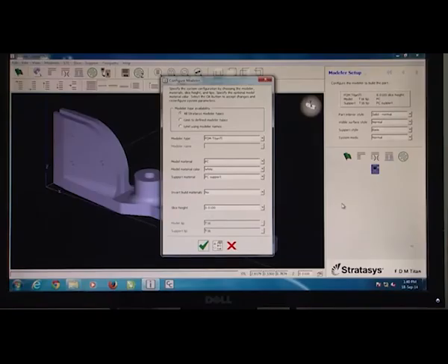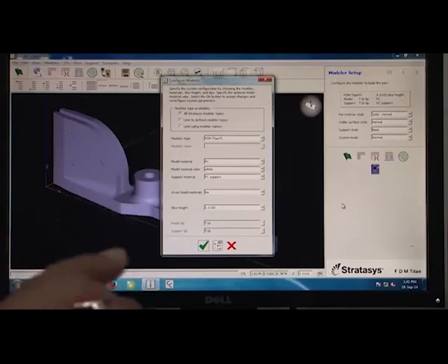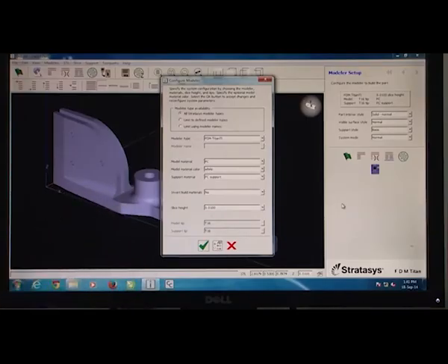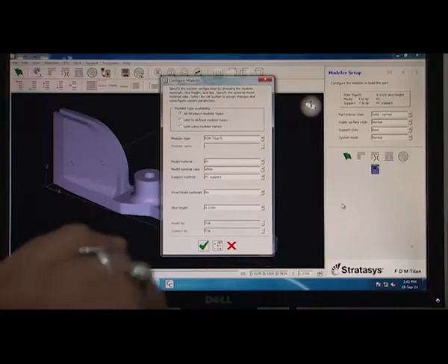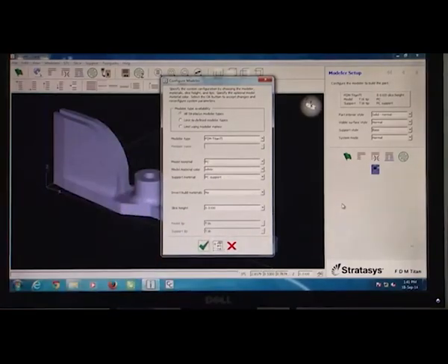We have to remember that there are about 4 nozzles in this system which has been delivered or specified by the manufacturer, and they are classified as different types, starting from T10, T12, T16 and T20. Each of them has a different orifice diameter, because ultimately if your slice height has to be more, naturally the dispensing rate also has to be more for the tool to actually be able to carve the object out.